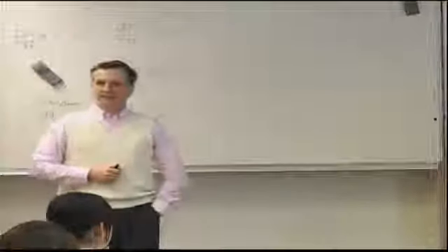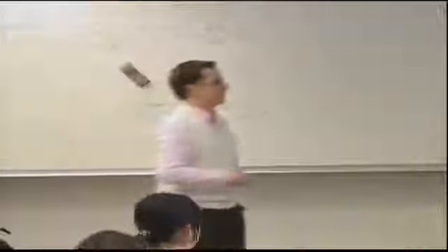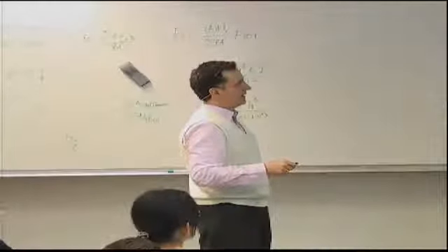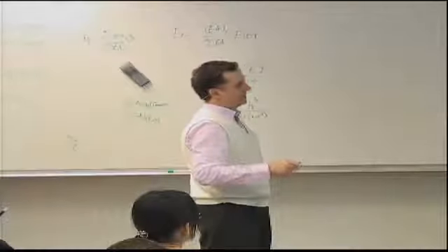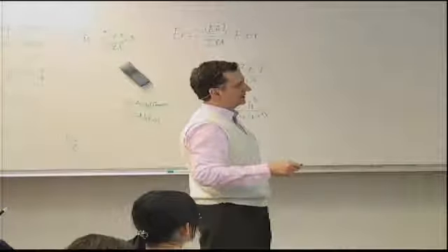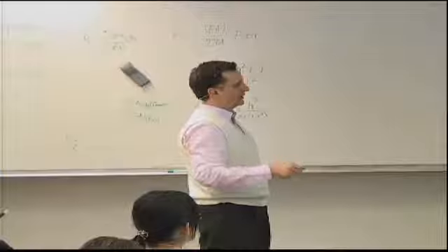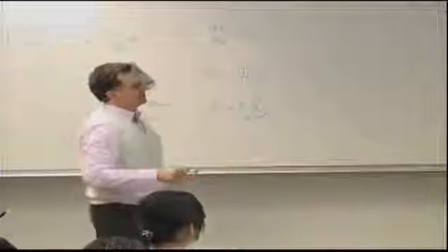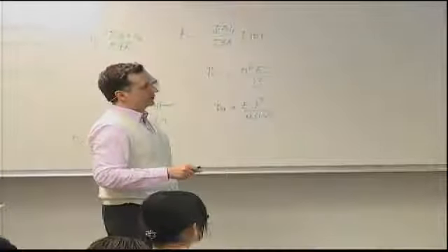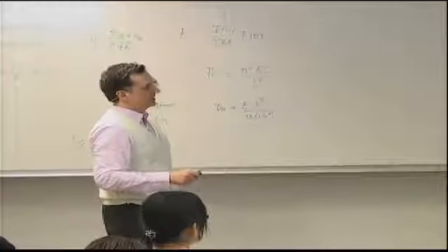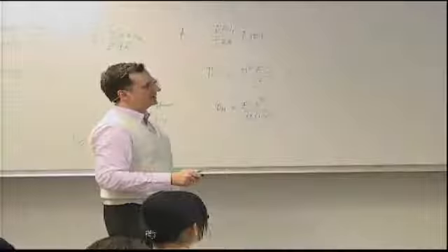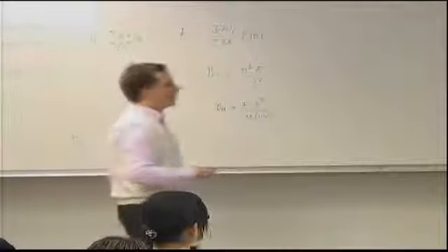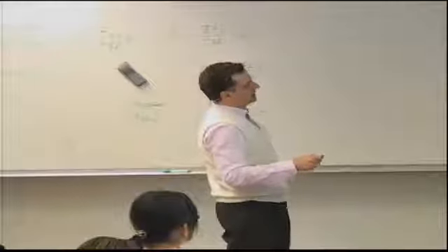Typically, a flange to width ratio is anywhere between 5 to 30, let's say. So on this axis, it is approximately in this region here from 5 to 30. What we see is that whether it's countersunk or protruding head, for any of these B over T values, the corresponding maximum fastener spacing is no more than about 20 millimeters.